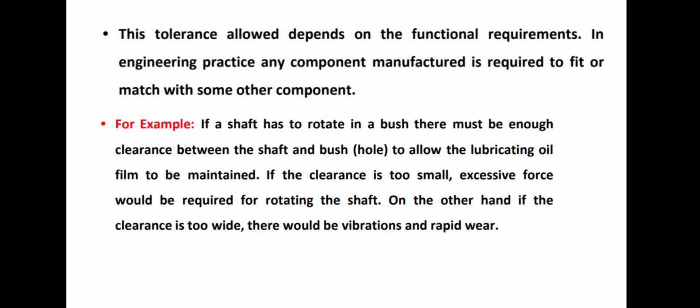If the clearance is too small, what will happen? Excessive force would be required for rotating the shaft. On the other hand, if the clearance is too large, the vibration will come.